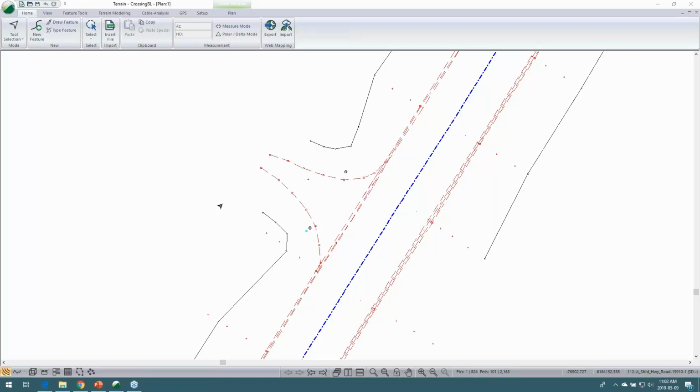Now, if we've got 2 different break lines, they both have defined elevations across their entire length. If they cross, we end up with a conflict, because even if the interpolated elevations are only a tiny bit different, it is a conflict when they are crossing. Of course, there is one notable exception: if 2 break lines share a crossing point, and they cross at the same point, there's no conflict.